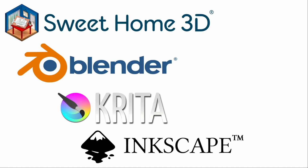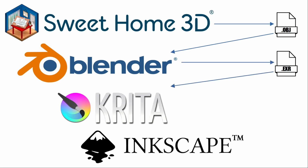So the workflow will involve using Sweet Home 3D, from which we will create an object file. That object file will be imported into a template file in Blender which contains our staging and the grease pencil that does the outlining and so on and so forth. From Blender we will export what is called an OpenEXR file. This is a multi-layer image file format. It can handle high bitrate and high dynamic range images. This EXR file can then be imported into Krita, which reads this format natively.